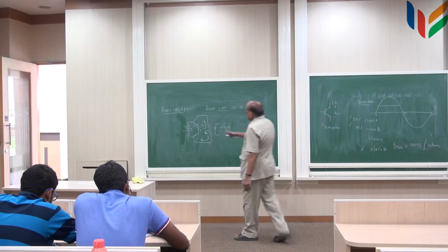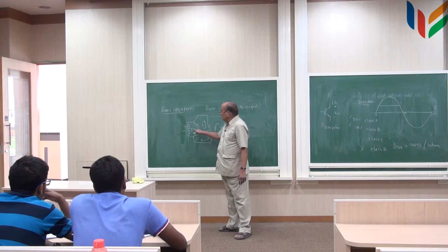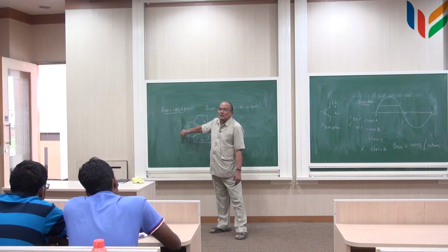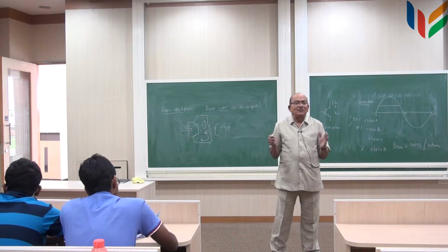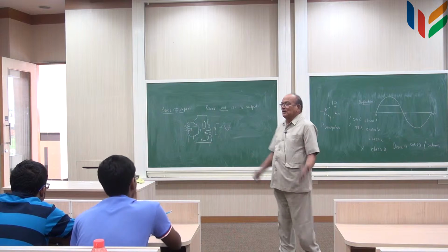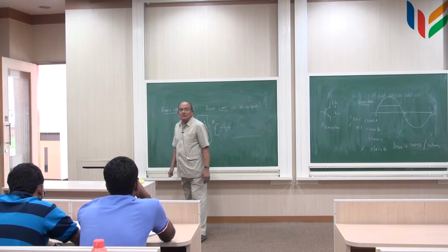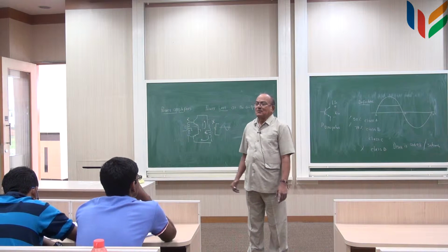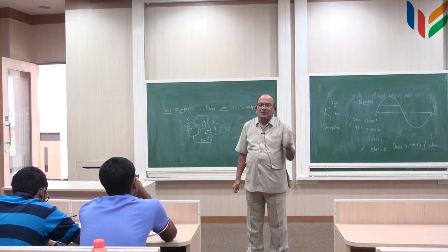So at that time people used this kind of a circuit using PNP transistors and then use two transformers, and the bandwidth of this transformer must be same as the bandwidth of the input signal here, at least with audio, which means this was a uniform bandwidth up to at least audio frequencies like about 10 kilohertz or 20 kilohertz or something, and that became a big problem. To make a transformer having that kind of bandwidth of 20 kilohertz, having a transformation ratio constant for all these frequencies. As you know that such a transformer will never transform DC, right?